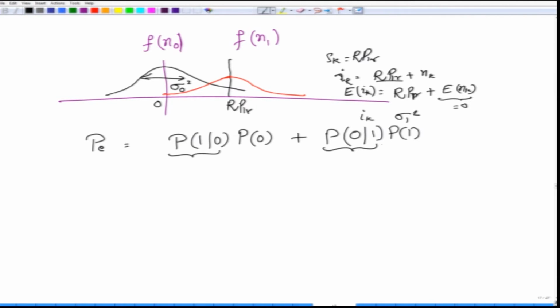If you are not catching this particular point, you can refer back to the ASE noise derivation. There we had the photocurrent given a certain optical power was received, and then we removed that preconditioning, right. So, we removed that conditioning, and that is what you get over here. Normally, you assume that you are transmitting zeros and ones equally, that is on the long run these probabilities are equal to half. So, you are left only to calculate the probability of 1 given 0 was transmitted and the probability of 0 when you have actually transmitted 1.